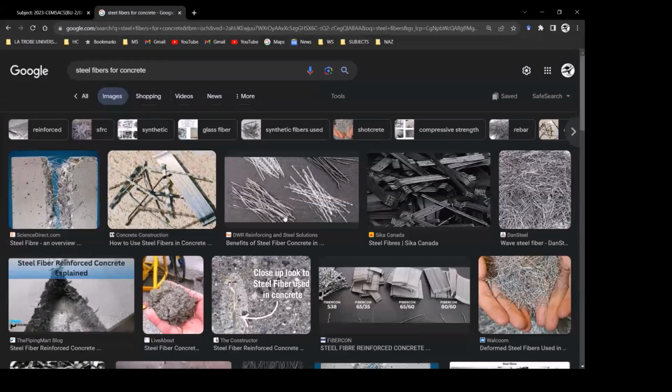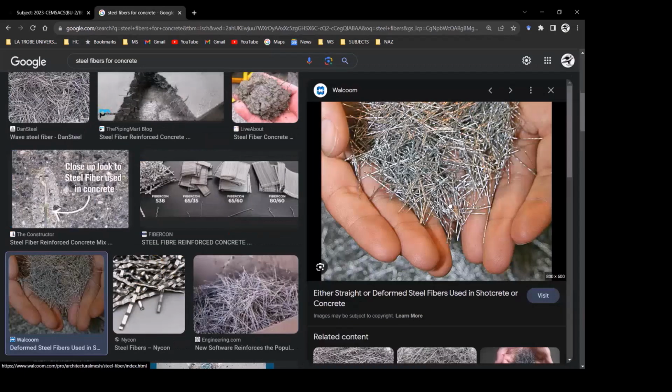These kinds of reinforcement, which are steel fibers, can be mixed with the concrete. And it's expensive, just to let you know. It's not really cheap. So the steel bars are cheaper, but this one gives you much higher quality. It controls the cracks very well. And if you need very minimum cracks, or micro cracks, which you can't see.